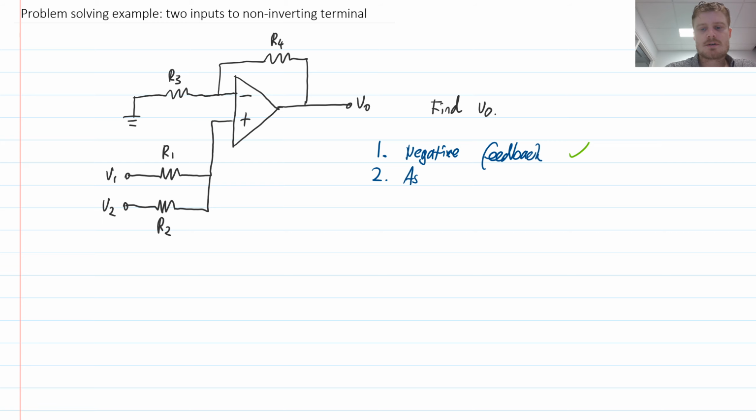So we will assume equal voltages. I'm going to call them VP and VN. So assume VP is equal to VN and IP equals 0 equals IN, where these are the currents that flow into the op-amp terminals. So those currents are 0. All right. Then step 3 is solve the circuit. So analyze it with those assumptions baked in.